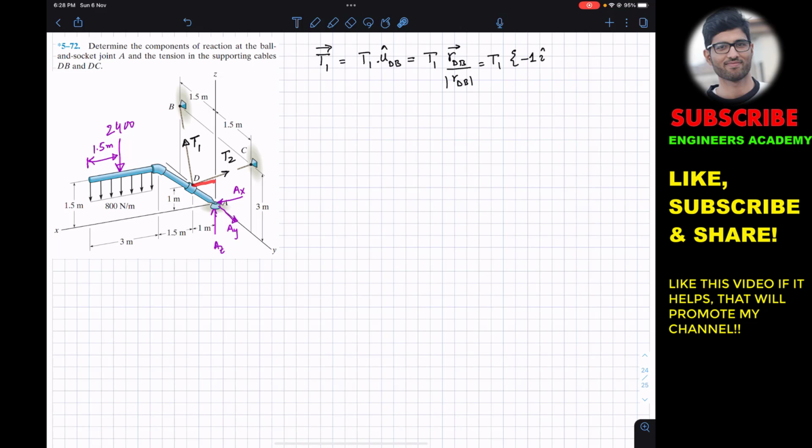So we will reach here, and then from here we need to travel this distance in the positive Z, and this distance is 3 minus 1, so this distance is 2. So we need to travel 2 meters in the positive K, so I will write plus 2K. Then we need to travel 1.5 meters in the negative J, that is in the negative Y. This is the positive Y, so we need to travel 1.5 in the negative J, so minus 1.5J. And then we have to find the magnitude of this position vector.